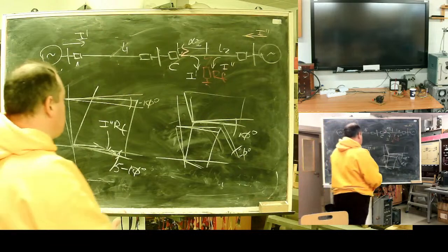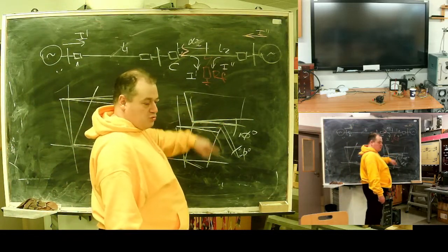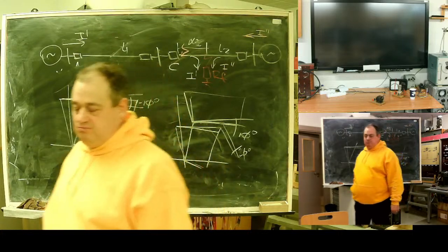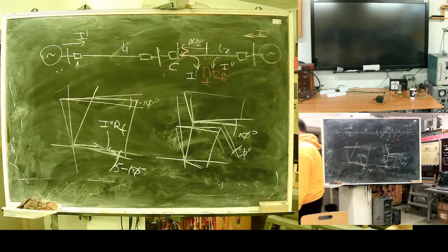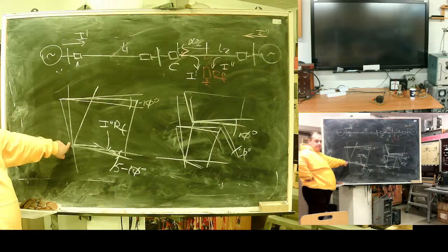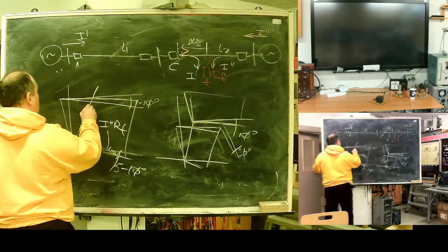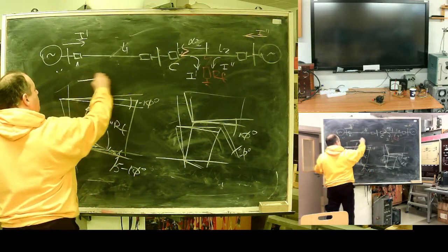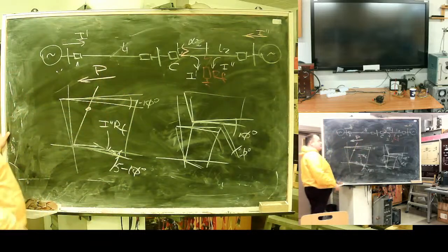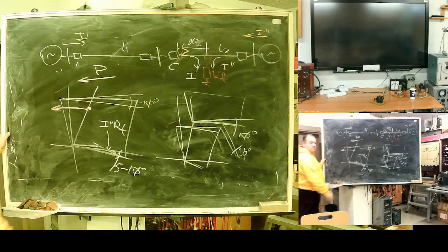And extreme care should be taken with a positive angle. Positive tilt causes non-selective operation. Next moment is this line. Why is it not straight? Because in case you have a fault and power transit was in the opposite direction, the vector of power transit will shift.